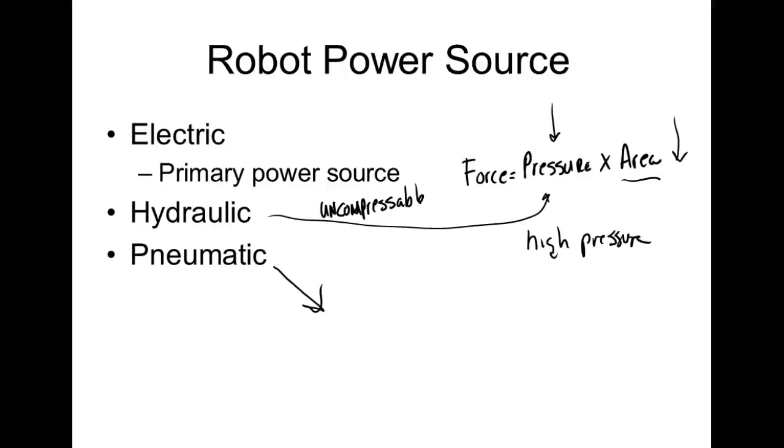With pneumatics, all our systems run at about 50, 60 PSI, which is pretty standard. So what can we use for tubing? Look at all the tubing on these robots running the gripper. It's just standard plastic tube. That means the system itself is a lot cheaper, right? The higher the pressure, the more expensive it's going to get to install.